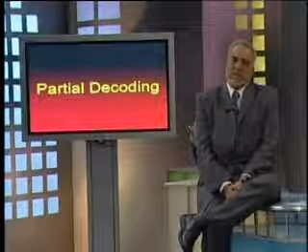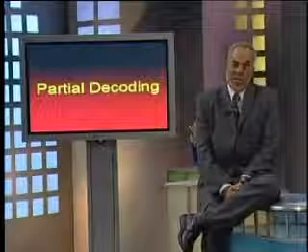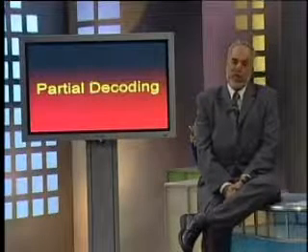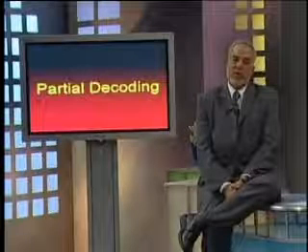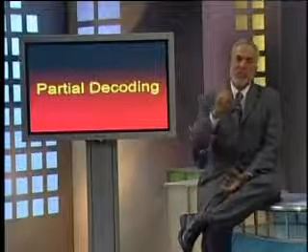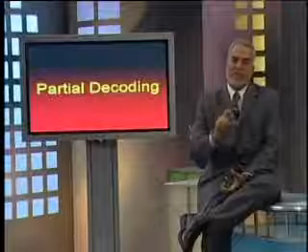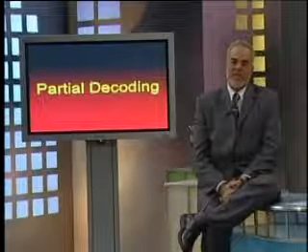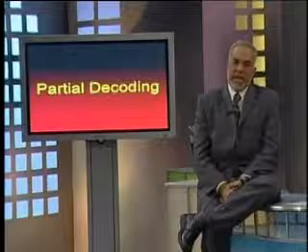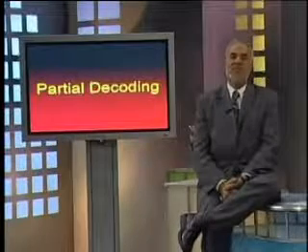The addressable space in this case would be 1K, and after 1K it would be wrapped around. We will have total 64K divided into 1K of each, and the address would be dictated by the lower 10 bits of the address bus.